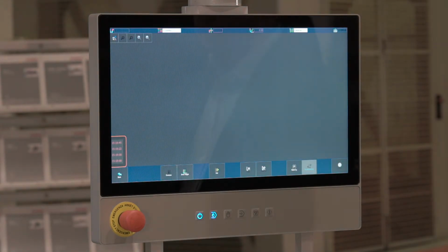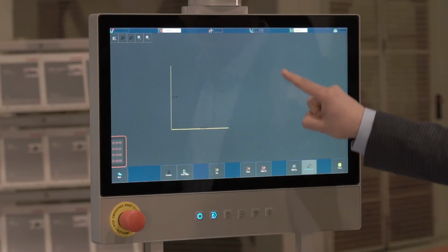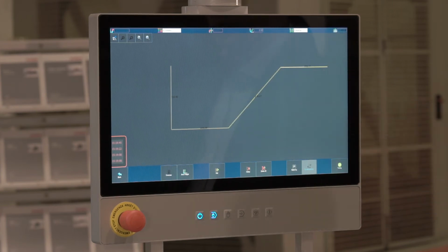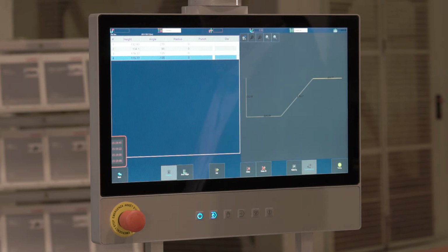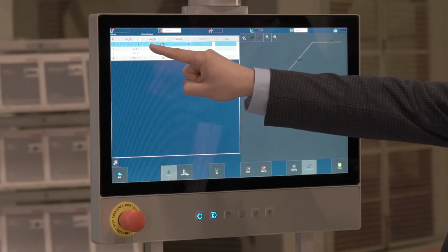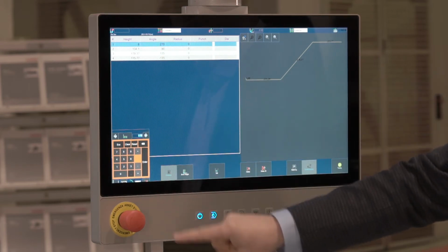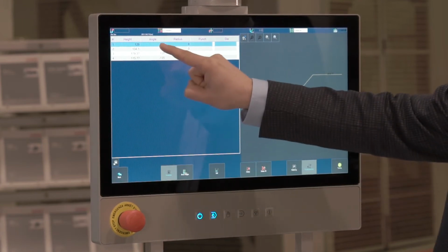Our screen is ready for drawing. On the screen, we create the profile of the part we want to bend. Then we can give our values after checking the back gauge distance and bending angles by pressing the Overview button. If I am to change the back gauge value and angle in the first bending, I can enter the distance value and angle by pressing it 2 times.